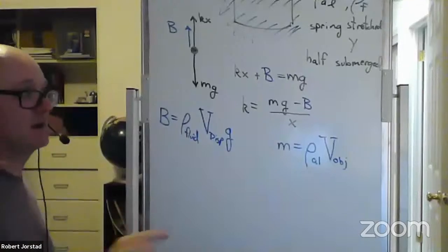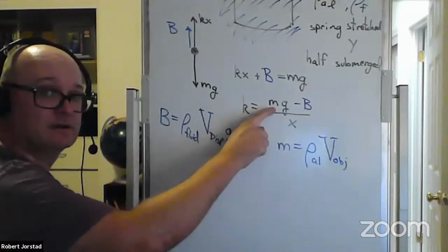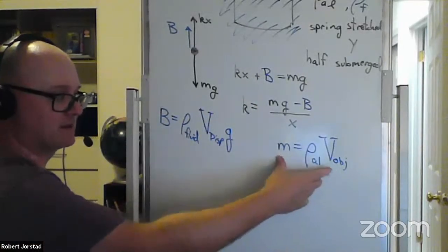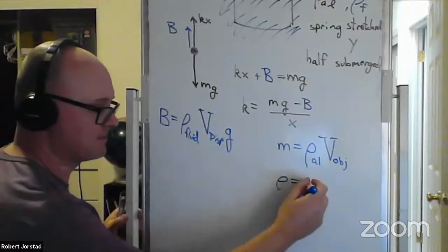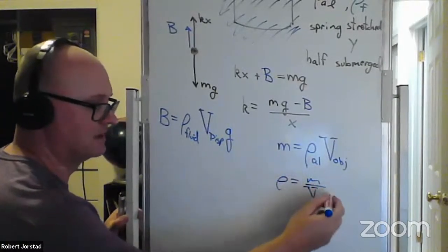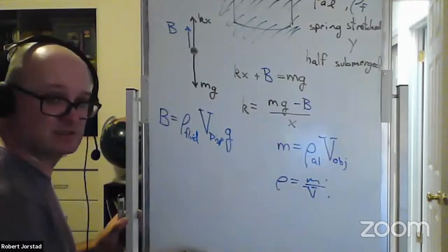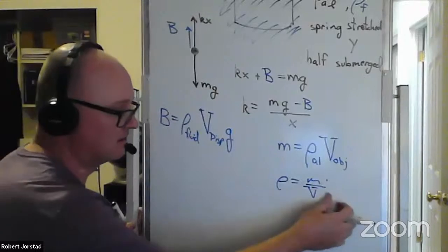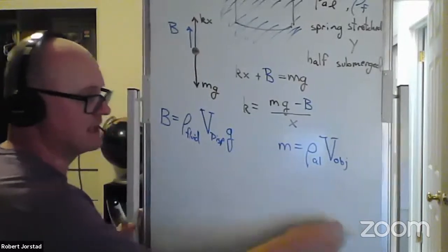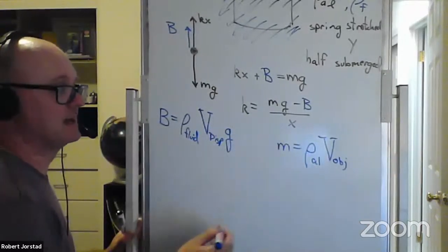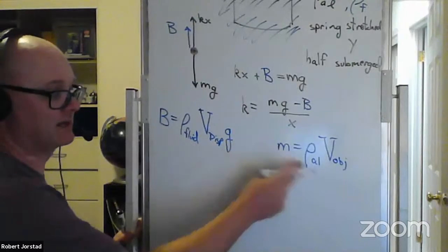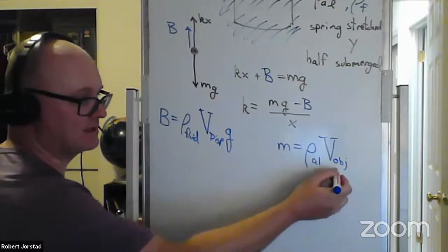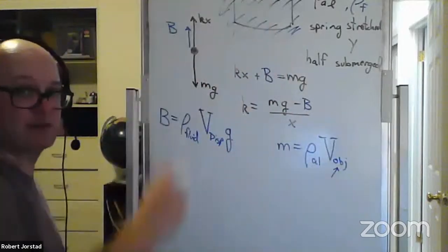All right, go ahead. Solving for the mass of the aluminum pipe. Do you agree the mass is not known? So I write down an equation that relates to the mass, right? We know that density is mass over volume, kilograms per meter cubed. Use the units to check it, or it's on the back of your equation sheet, on the back of your book. So you rearrange that for this. And so the idea is, I don't know mass, but I do know the density, and I think you could tell me the volume from that information that was given.